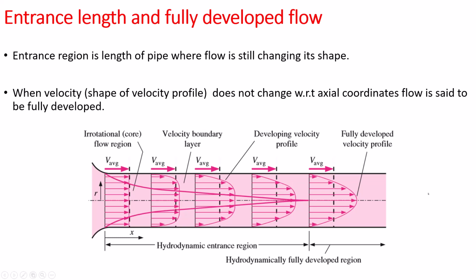So what are the assumptions now? The only velocity we have is in the x direction, that is ux. The v, which is the velocity in the y direction, is equal to 0, and there is no velocity in the z direction, so this velocity is also equal to 0. Number two is that for the whole circle, there is no variation of the flow along the angular coordinate, meaning that the theta direction will be 0.